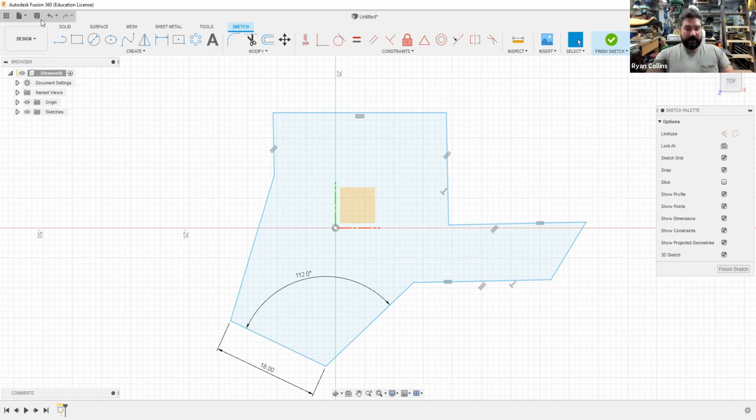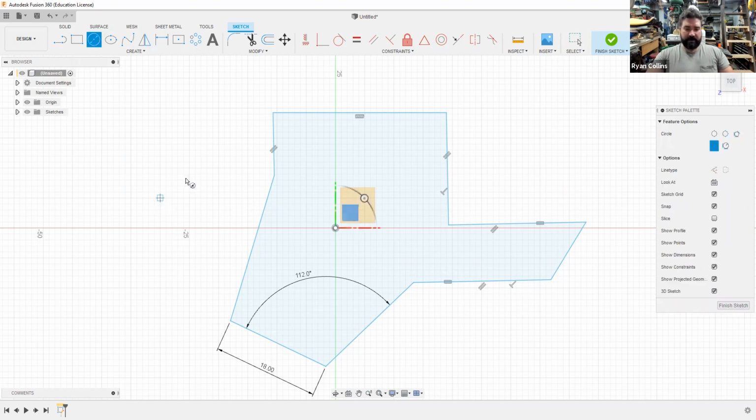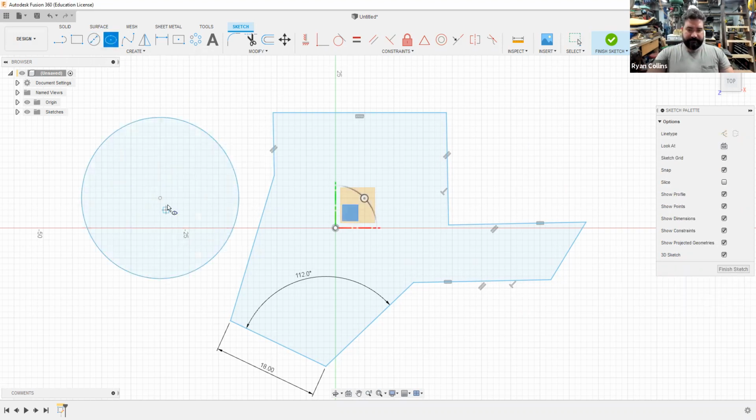You can apply all manner of stuff. Circles, starting from center circles, means that if you start from one point and draw outward, there you are, hit escape. You can draw ellipses. Start from the center, pick one point going out, pick another point going up. Now you can start to build more things.